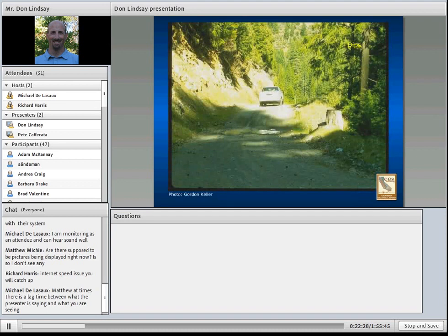Here's a photo of a large rolling dip. Although this is a good example of a well-pronounced rolling dip, it may not be able to accommodate low, long wheelbase vehicles such as lowboys or chip vans. Keep in mind, if you are designing and building a road, you must consider the limitations to prevent this from occurring. It is best to outslope and maintain dips with a minimum slope of about 5%.